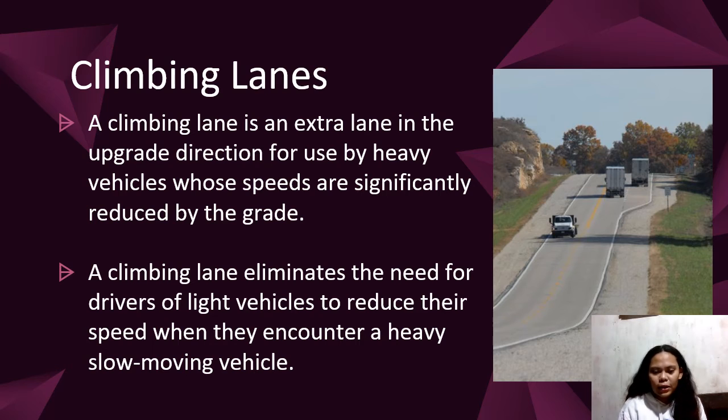A climbing lane is an extra lane in the upgrade direction for use by heavy vehicles whose speeds are significantly reduced by the grade. A climbing lane eliminates the need for drivers of light vehicles to reduce their speed when they encounter a heavy, slow-moving vehicle.